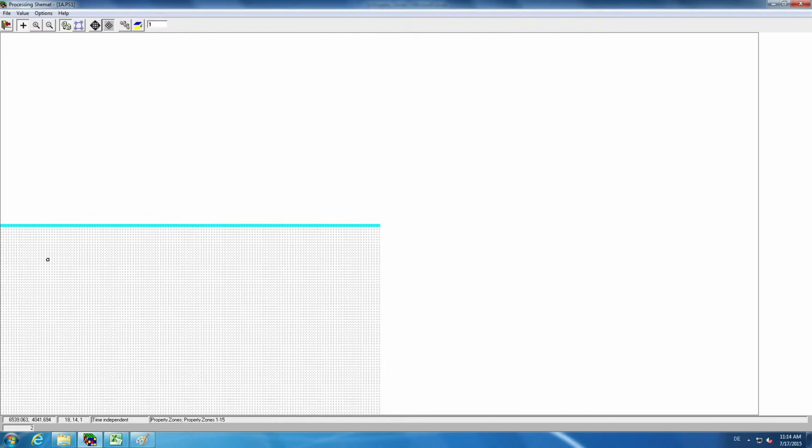Alternatively, you might have used the editor directly to define property zones, either by cell input, the 4th icon from the left, or by zonal input, the 5th icon from the left, and by switching between duplication on or off, 2nd icon from the right, as you need while using the left, right, up or down arrows to move the cursor for marking grid points you wish to assign to a specific layer.